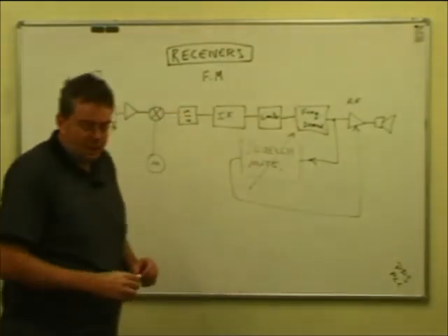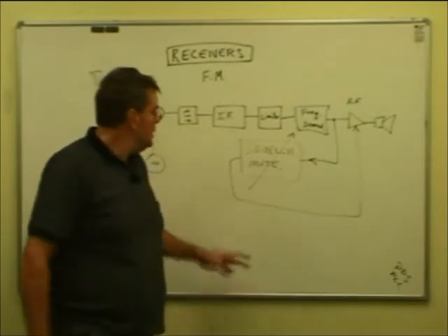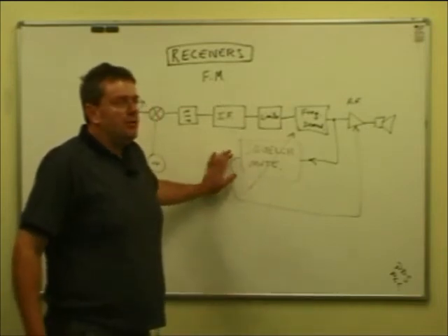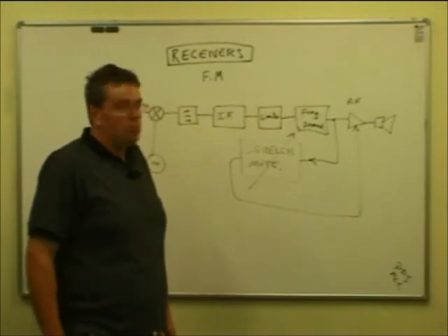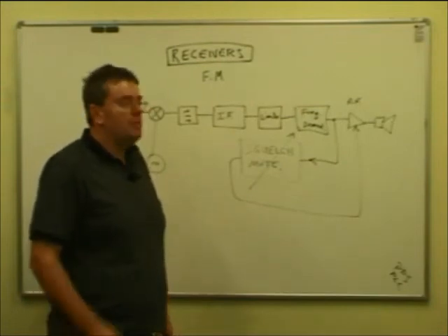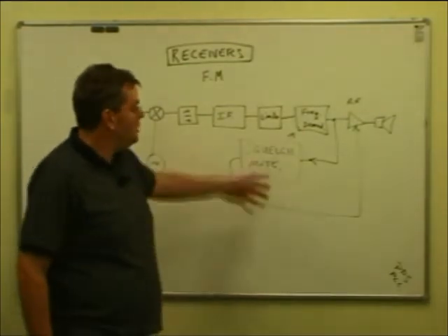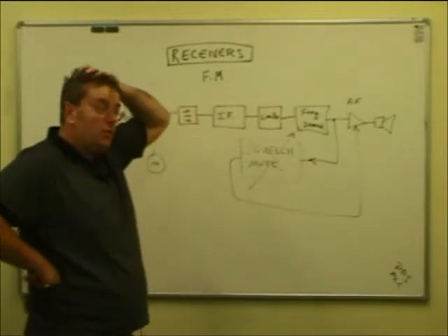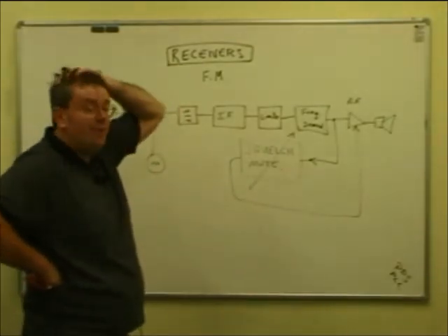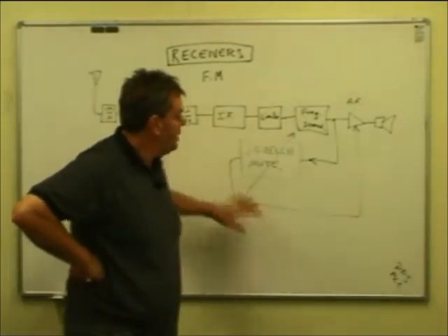The more modern handhelds, there's not enough knobs to go around, so often it's preset internally on a menu option. The reason it's adjustable is that if you're in a very high noise environment, it's often the mute will start to open. When I mean noise, like local signals and interference and rubbish, and sometimes you want to actually make the system require a cleaner signal, if you like. I don't know if it's explaining it well, but it is useful to have the threshold, if you like, at which it will allow a signal to come out adjustable.